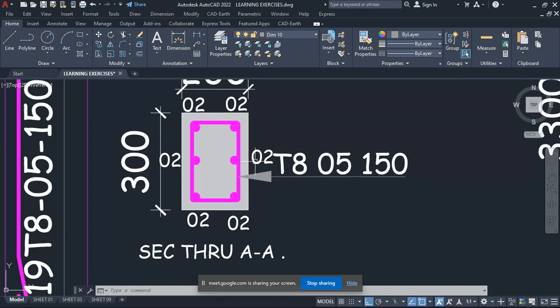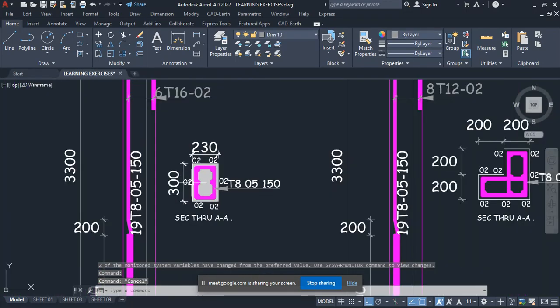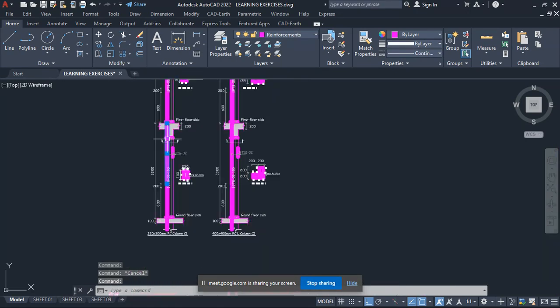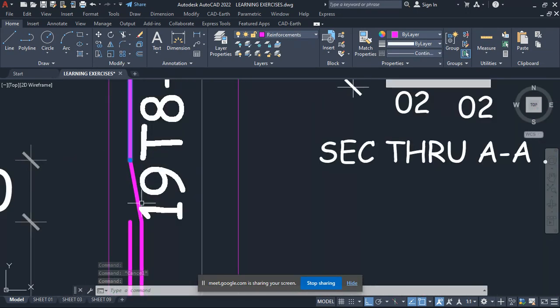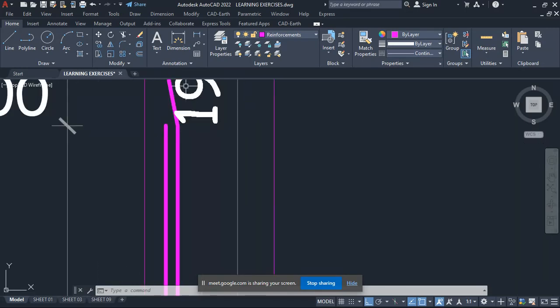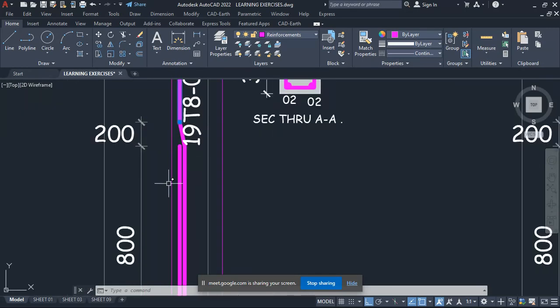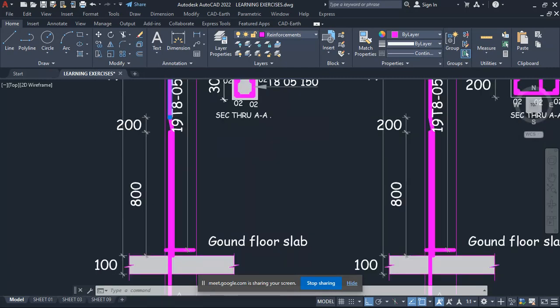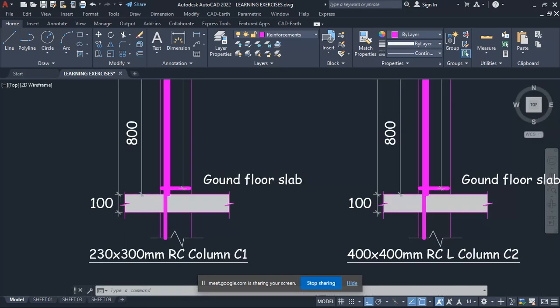With the bar mark, this 0202 is a bar mark for the vertical bar, which is this one here. So here you're showing that it is moving. You're seeing here there's some lap. Now for bar size 16, your lap should be at least 700. So 800 is okay, to 1 meter. So this is where the bars are lapping from on the ground.